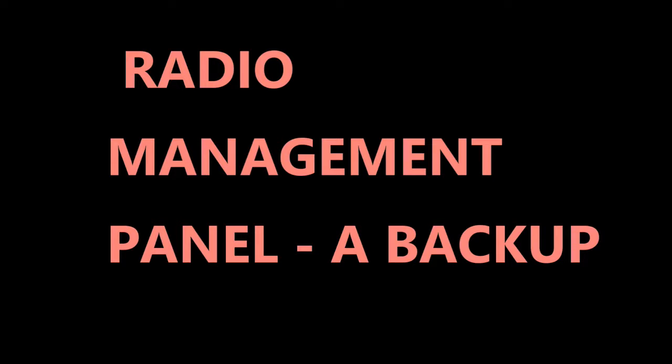So you've got your active frequency display, okay, for output by the management panel. Okay, so what's going out. And then you also have a standby course display, and those are just your preset frequencies on that window, or that sub panel, if you will. Okay, you do have a selector indicator light. That's going to be an amber, and that's just to indicate the interactions between the different RMPs. So the SEL indicator light is for that purpose. You have an AM push button switch for high frequency.